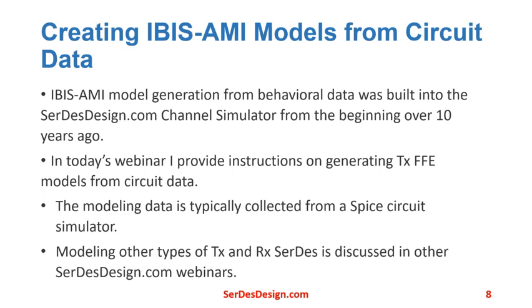Creating IBIS-AMI models from circuit data. IBIS-AMI model generation from behavioral data was built into the SerDesDesign.com channel simulator from the beginning. I have used this process over the past 10 plus years, providing custom IBIS-AMI models to over 40 companies based on the circuit data they provided to me. In today's webinar, I provide instructions on generating transmit FFE models from circuit data. The modeling data is typically collected from a SPICE circuit simulator. Modeling other types of transmit and receive SerDes is discussed in other SerDesDesign.com webinars.